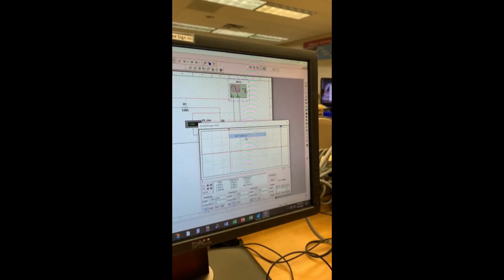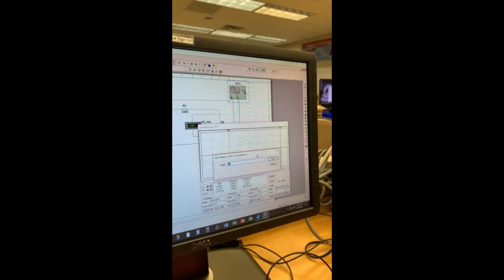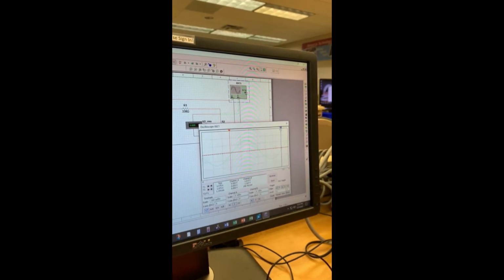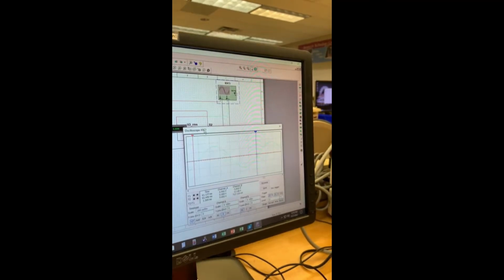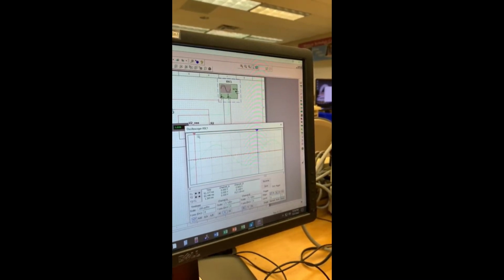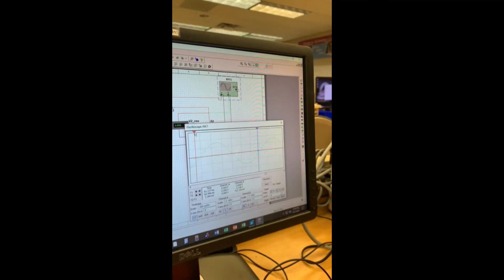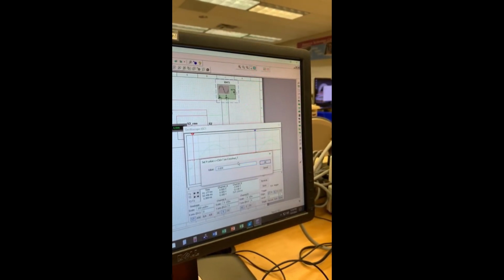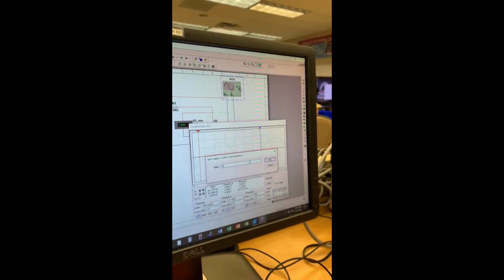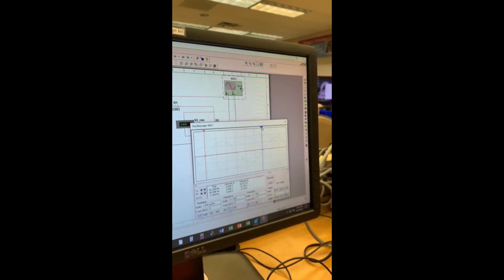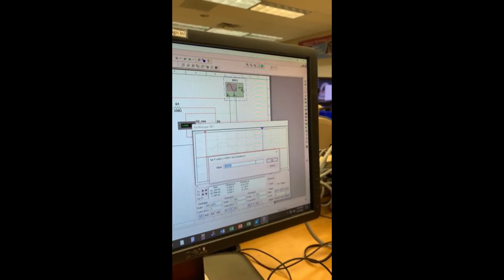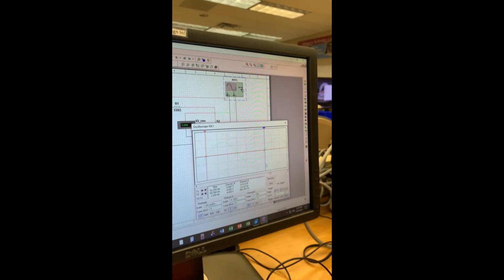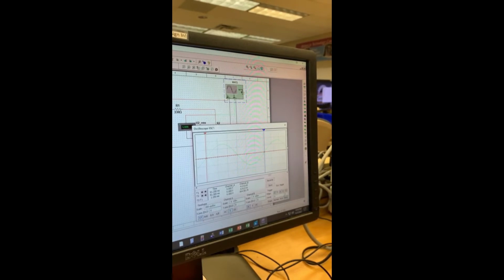And for the period, let's go to the start. We're going to set this to 0. Let's make sure that this time I got the circuit right. There we go. 0, and same thing here, 0. To get the period, we're going to do the same thing as we did in channel 1. We set the value to 0 here and the same thing right here. And just like that, we get the period, which is 1.250 ms, the same as channel 1.